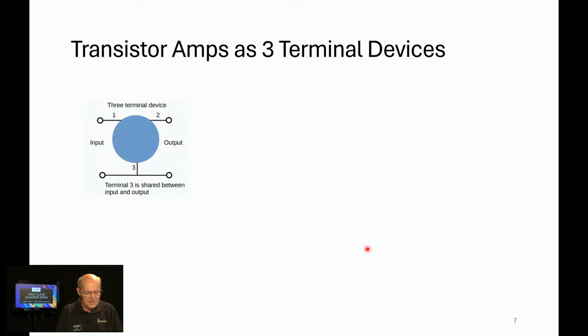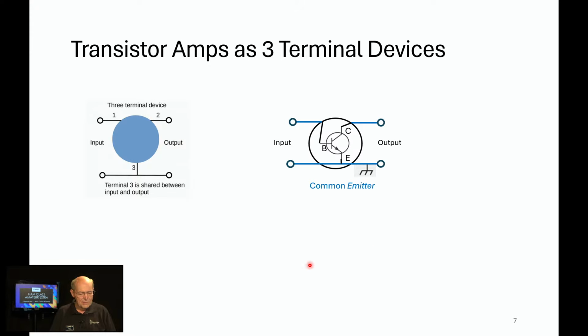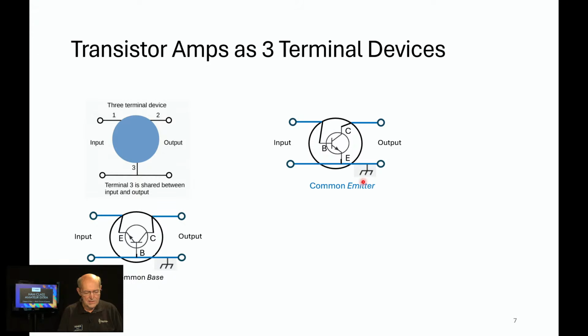All right, so how do we apply that? Well, we're going to plunk a transistor into that circle. In this case, we've got what's called the common emitter case, and you'll see that that's in blue. We're going to need to identify what a common emitter configuration is for our pool questions. So we've got the input across the base and emitter, and the output across the collector and emitter. You can see why it's called a common emitter. And then we're going to rotate this 90 degrees.